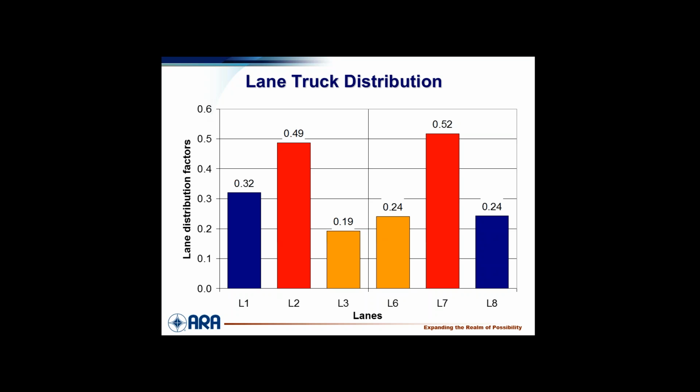A local university got students out there and identified which lane all the trucks were in for quite a few hours. This was the breakdown of trucks. There's the outer lane, there's the middle lane, there is the inside lane, not the bus lane. The bus lane would be the next one over. Now this is like the tollway. This is exactly what happens on the tollway. We've measured this many times. You have more trucks on the lane over than on the outside lane. Look at that, double. You double the trucks here that you do here. Same here.